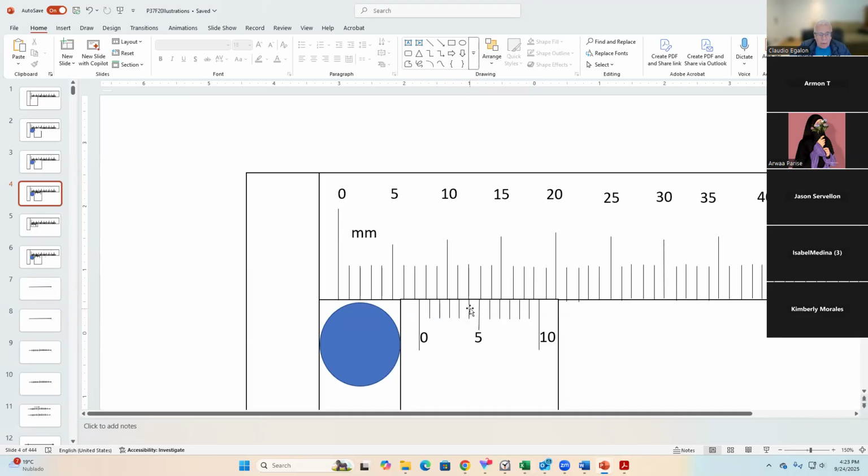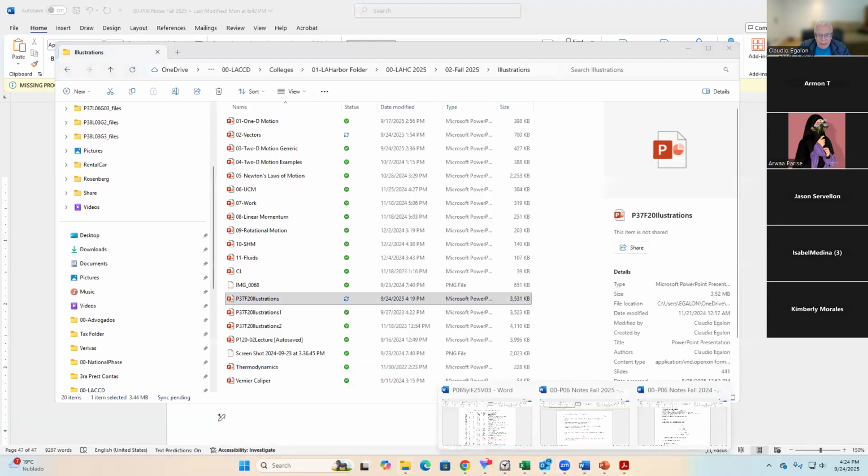It looks like until we reach this other one right in here, that's very closely aligned with the other one. If you go to the next one, you can see that it's already jumped, right? It's too much to the left. And then the other ones keep on going further and further away. So from this measurement here, I can tell you that this device is measuring 7.4 millimeters just because of the vernier scale. Okay? So you get the idea of the vernier scale?